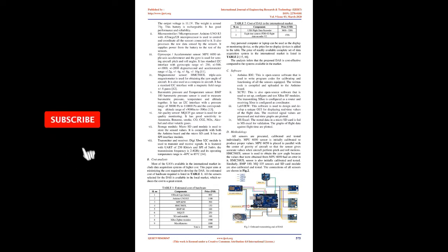A. Hardware. 1. Battery. An Orange 850 mAh 30C lithium polymer, LiPo, battery is used as a source of power for the DAS. The output voltage is 11.1 V. The weight is around 75 g. This battery is rechargeable. It has good performance and reliability.